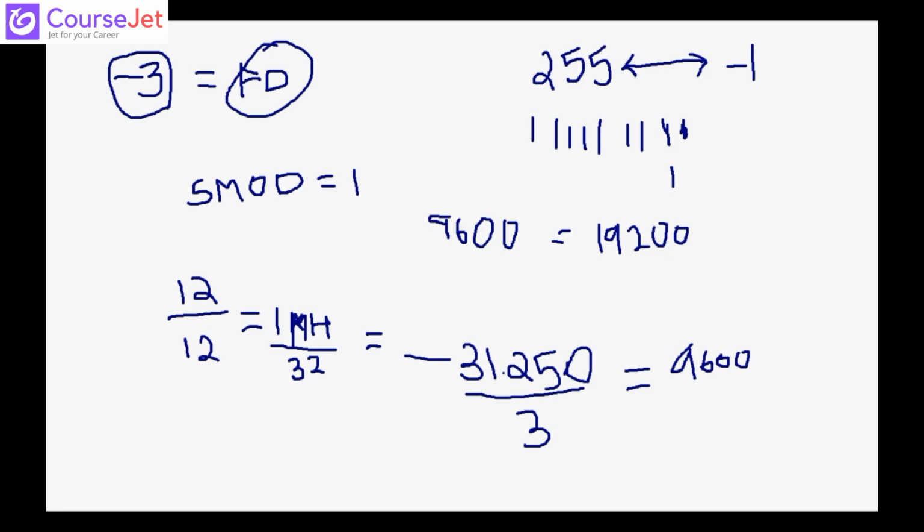Now, as I said, first thing we need to do is select the speed. But when you want to use a timer, first you need to select a timer. We are using timer 1 mode 2, which we can select in the register called TMOD. So the value for TMOD will be 0x20, which is timer 1 mode 2.